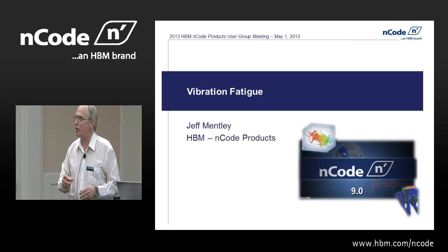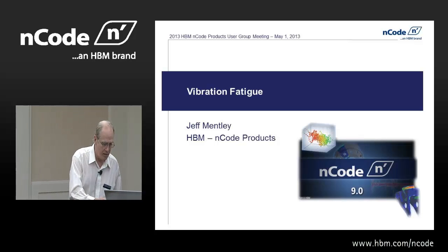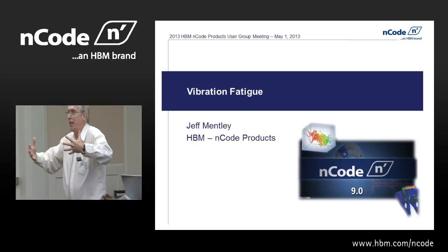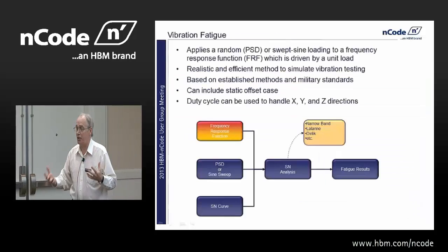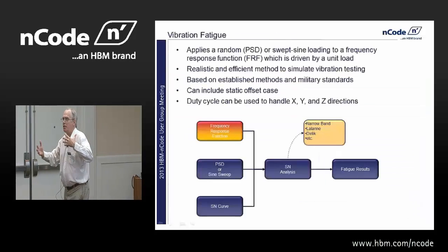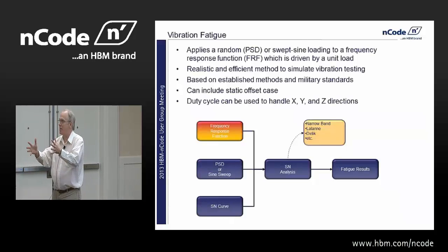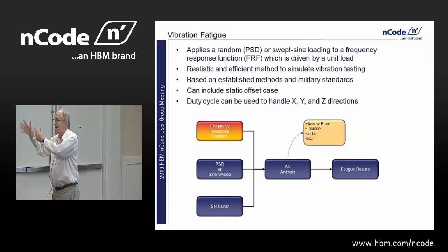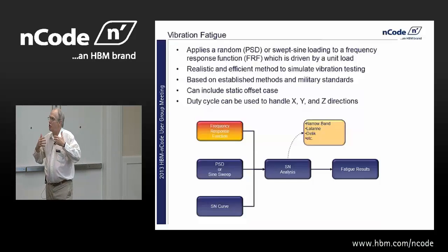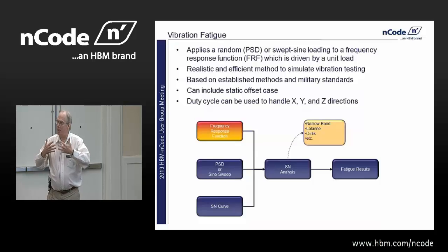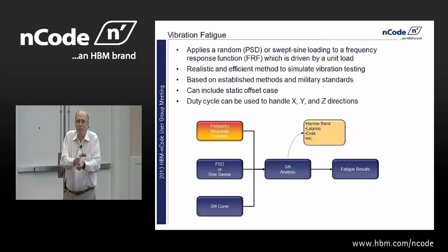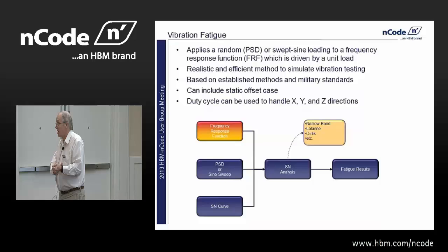We're going to talk about vibration fatigue. Vibration fatigue is our marketing name for doing fatigue in the frequency domain. Most of the things we've seen today, we've brought in time histories or time elements and basically rainflow counted the time signals. Here we're talking about looking at a frequency-based input, either swept-sine or a PSD input.